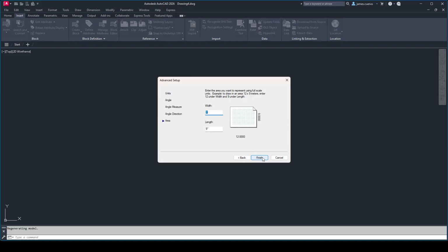And the reason why I'm making that very specific distinction here is because remember, if your limits are on, you can't draw outside that border that you're defining, that area that you're defining. If your limits are off, you can. You need to keep that in mind.